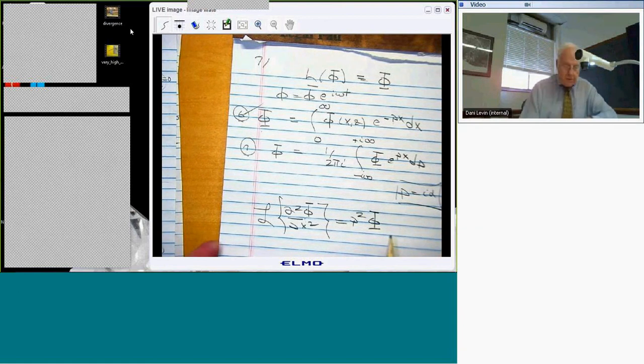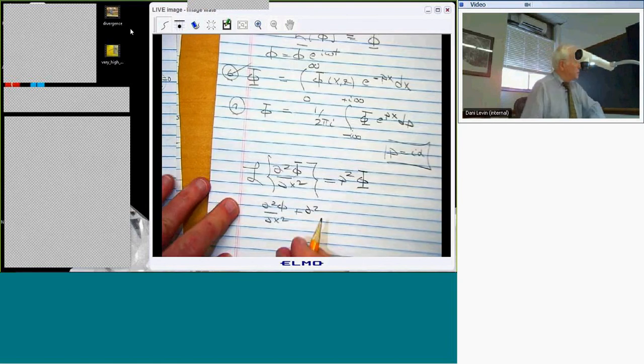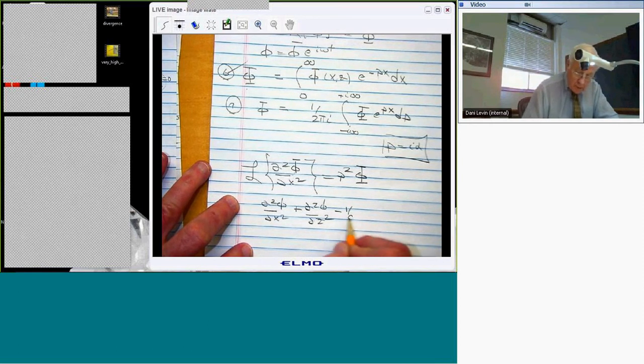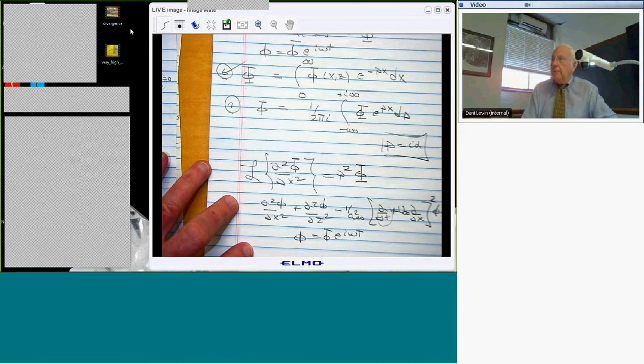Okay. So now, if I go back to my differential equation, d/dt plus u infinity d/dx squared phi equals 0. And now I assume that phi equals phi bar e to the i omega t. So every time I see a d/dt, I replace it by i omega. And I take a Laplace transform of the entire equation. So every time I see a derivative with respect to x, I have a p, right?